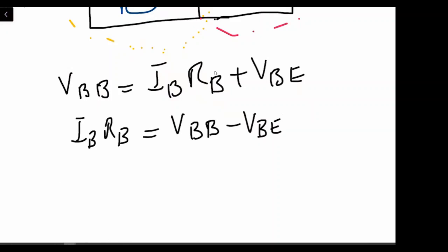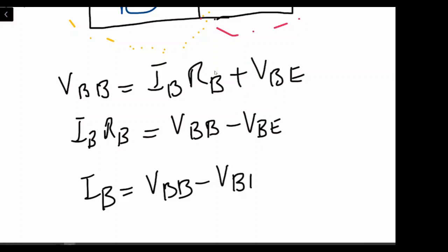Yes, sir. Or we can say IB is equal to VBB minus VBE divided by RB, right?